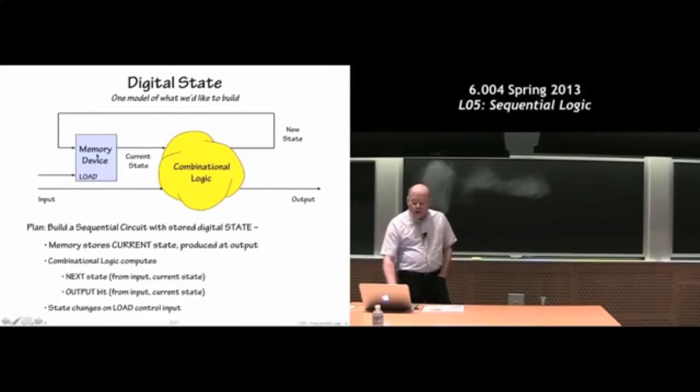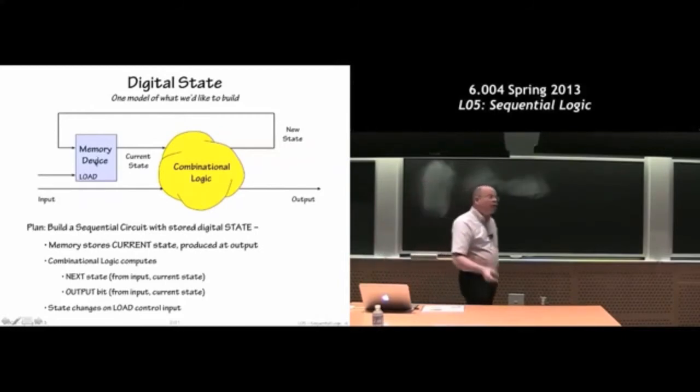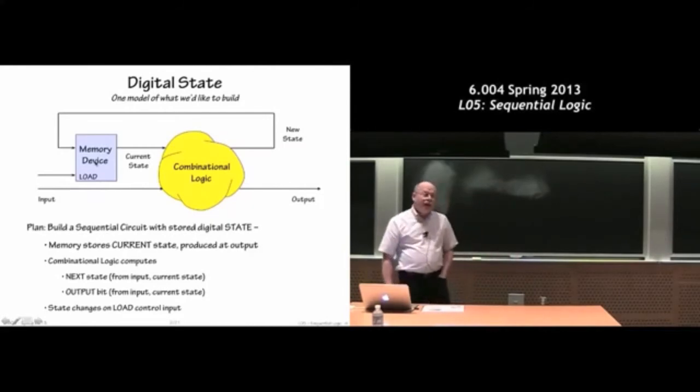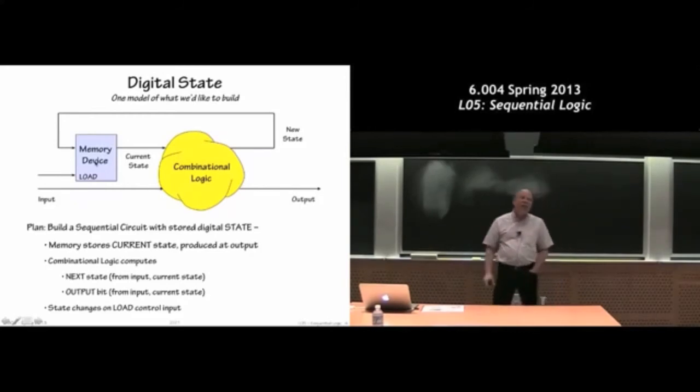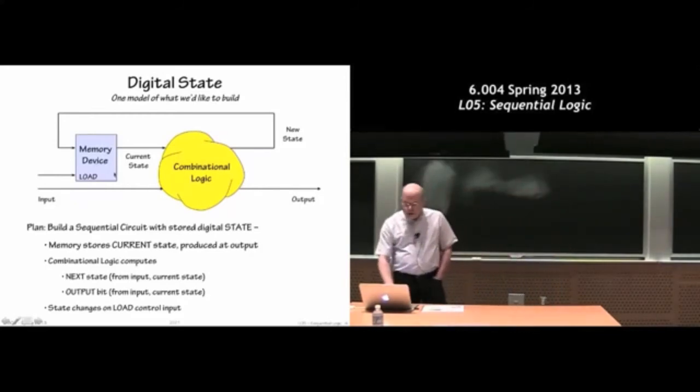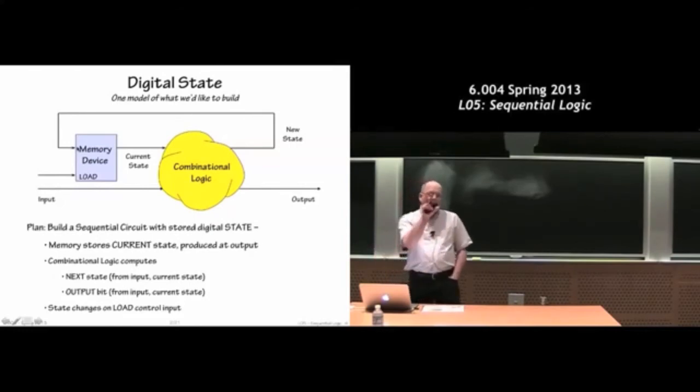And you'll discover in a moment that the actual circuitry that we're going to use to build a memory device is itself not a combinational circuit. It will be a circuit that itself has a positive feedback loop in it. That's how the storage will be implemented stably. So it's a good observation that, in fact, we're breaking our notion of allowing ourselves a cycle, but they're going to be engineered cycles. You can't willy-nilly make a cycle. You can only make a cycle, in a sense, at the input and output of a storage device. Okay, so cycles that don't include one of these storage devices will continue to be disallowed. We won't allow combinational cycles.